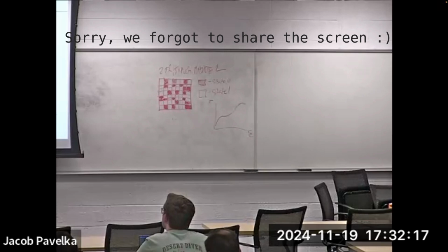In this block, you're defining your mesh parameters. Initially, I'm going to divide it in the X direction in 5 places, and in the Y and Z direction just once. Then you can set this refine factor: how many times do I subdivide all of those elements again to make a finer mesh?